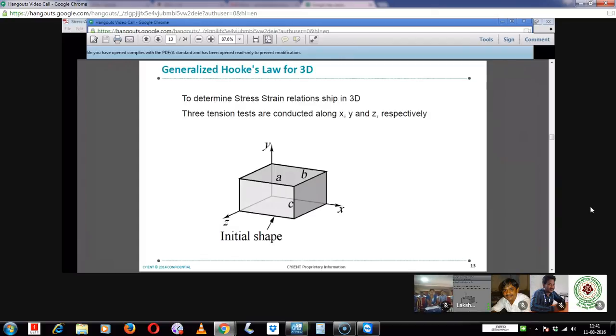But when you want to solve a fan blade off, meaning releasing one blade, an impact event, then a single blade is not a good idea. We have to use all the blades so that we can see the impact of one blade releasing on the adjacent components. So that is the reason the type of analysis is more important, and the type of loading also will drive. When loads are symmetric, we can assume a lot of things. When loads are not symmetric, then we cannot assume. So loading and type of analysis are very important while doing this model idealization.